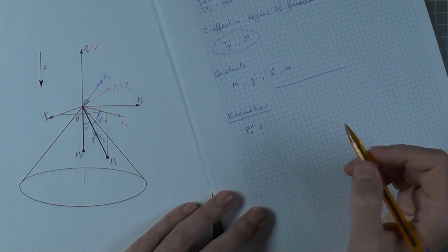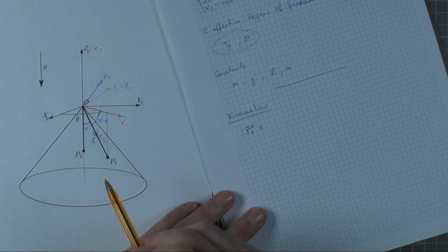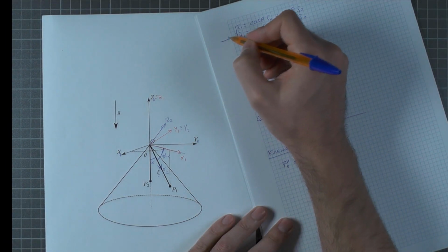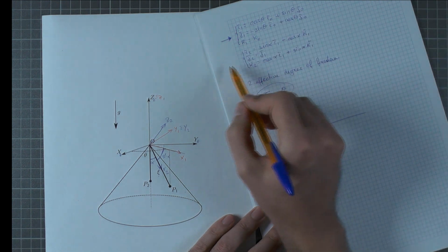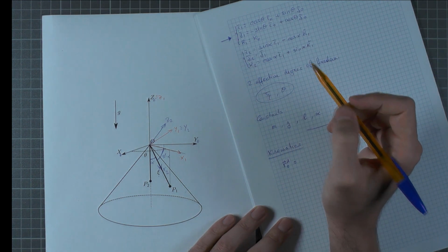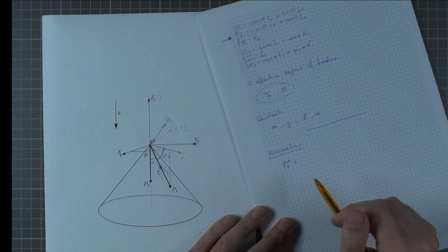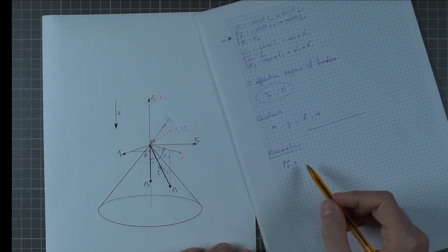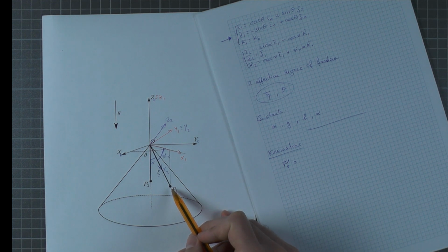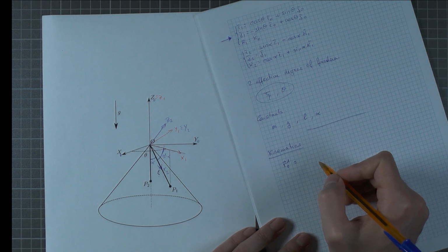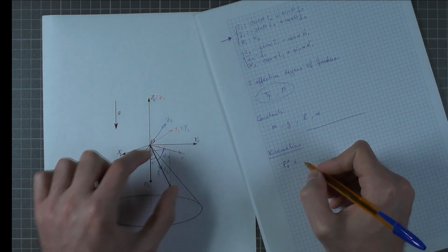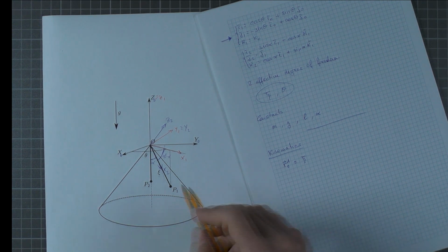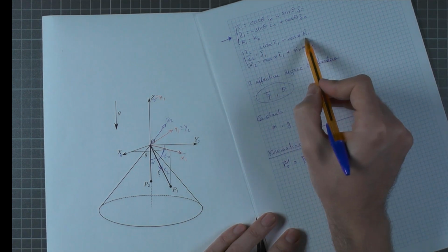We write down this position using the red reference frame here, so I'm only going to use this vector basis. As I said, I could be using this other one, but in my experience, this one is enough to solve the problem, so let's just stay with this one. So the position of P1 is essentially on the surface of this cone, and it is a distance h from the origin, in the direction of I2, which I have over here.